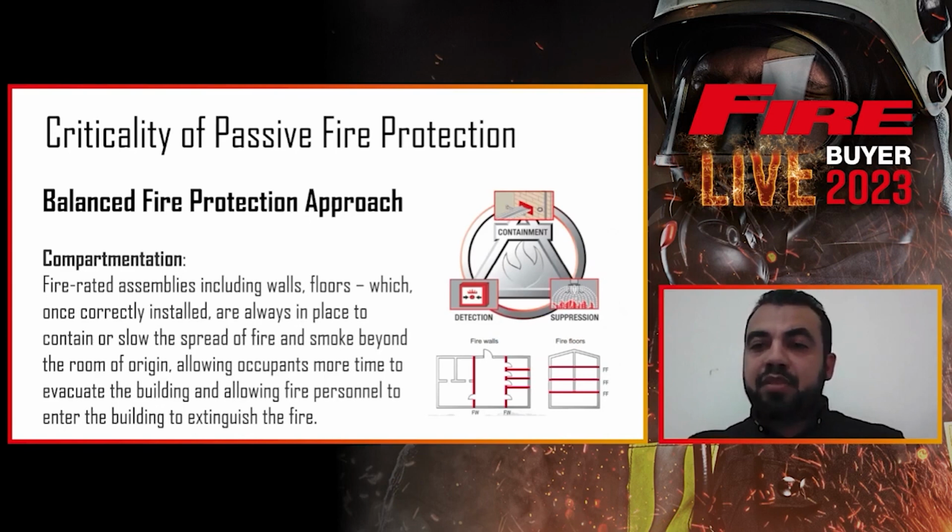Managing the fire impact could include containment by structure, detection to give an alarm for people to evacuate, and active fire protection systems like sprinkler systems. It will not be based only on active fire protection, but the containment of the fire is very important.